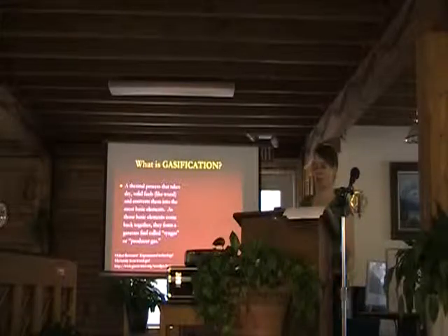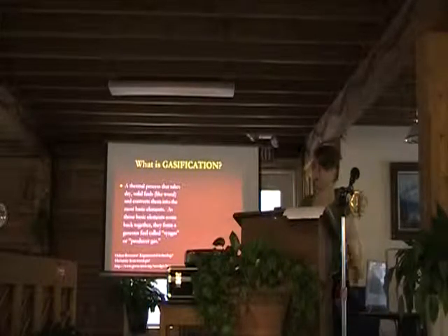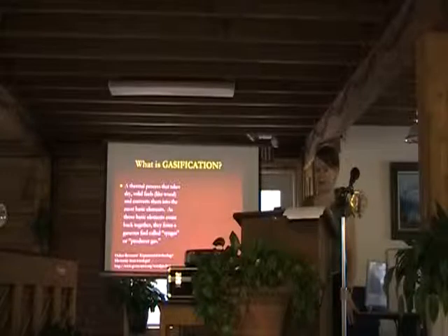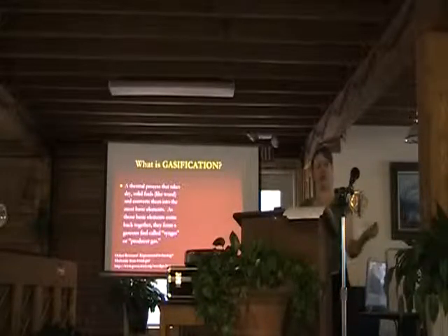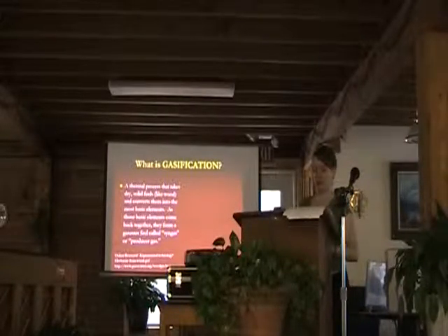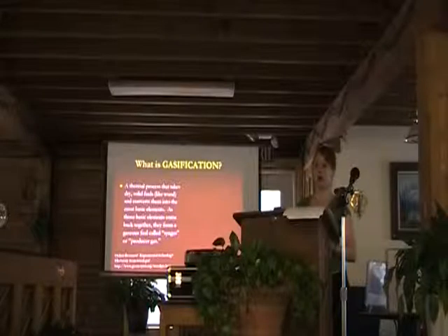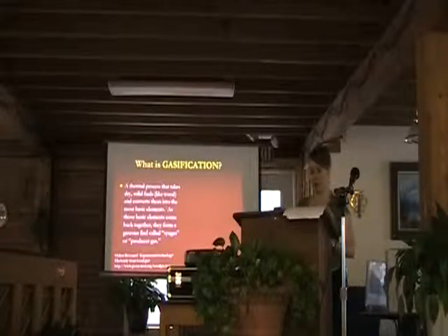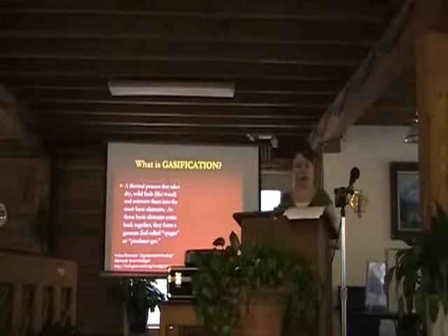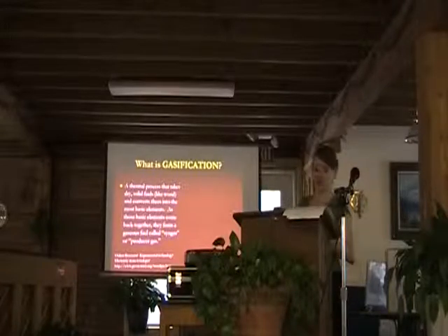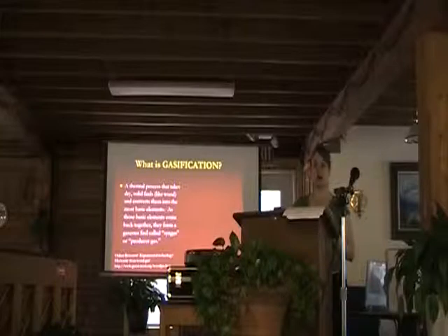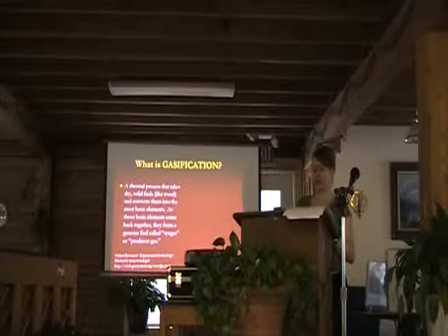is the thermal process that takes dry solid fuels, like wood, and converts them into the most basic elements. And then as those basic elements come together, they form a gaseous fuel called syngas, or producer gas. In our case, it's called wood gas because our medium that we're using to burn is wood. And so it takes the wood, it converts it into carbon monoxide and hydrogen by reacting the raw material at high temperatures, upwards of 700 degrees, with a controlled amount of oxygen and steam.